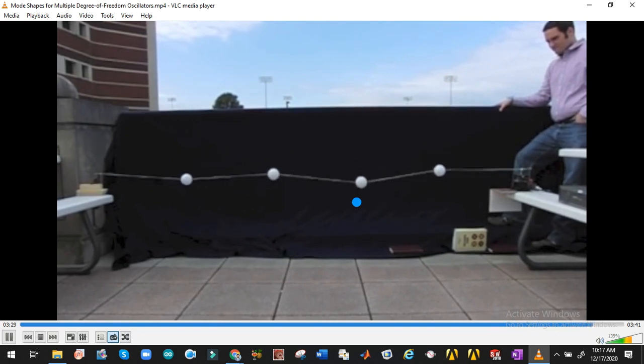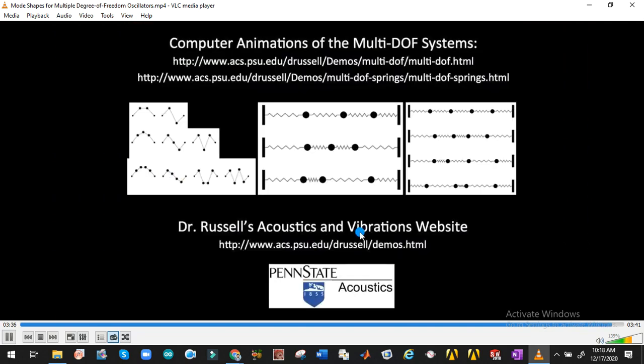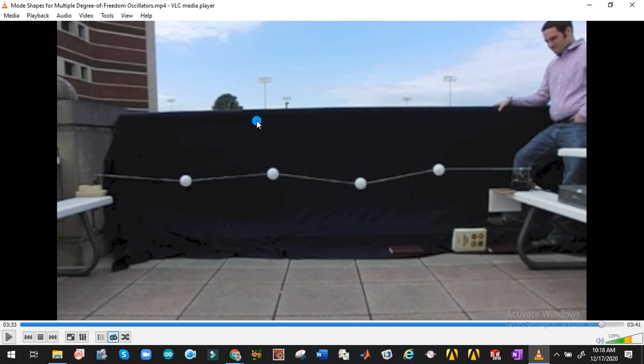Okay, so we will solve all of these systems analytically. How can we find the possible mode shape? For example, if this body is vibrating at the fourth mode in this way, how did they come to this shape? We will find out the possible amplitudes that each mass can carry, and we will connect them with the antinodes, and finally we will have the possible type of mode shape.